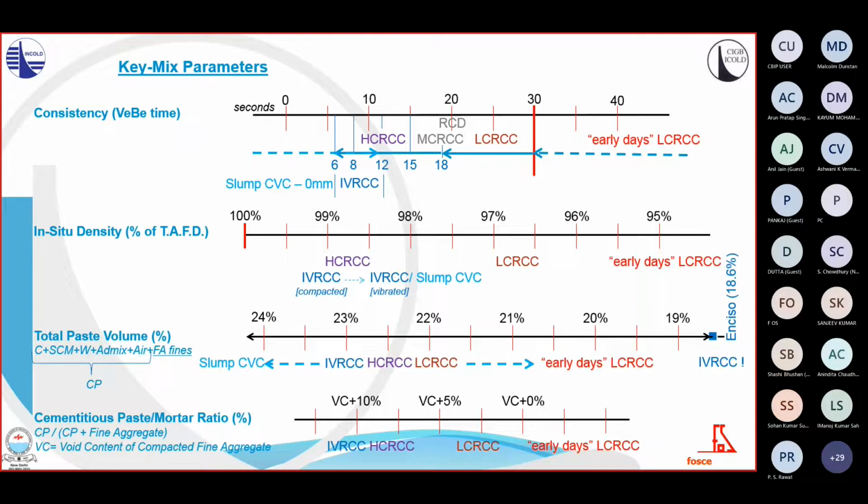Conversely, the paste volume of early times lean RCC mixes could hardly fill the voids in the matrix, but nowadays, with the increased workability in all types of RCCs, most of them manage to bring some excess paste upwards to the lift surface during compaction.